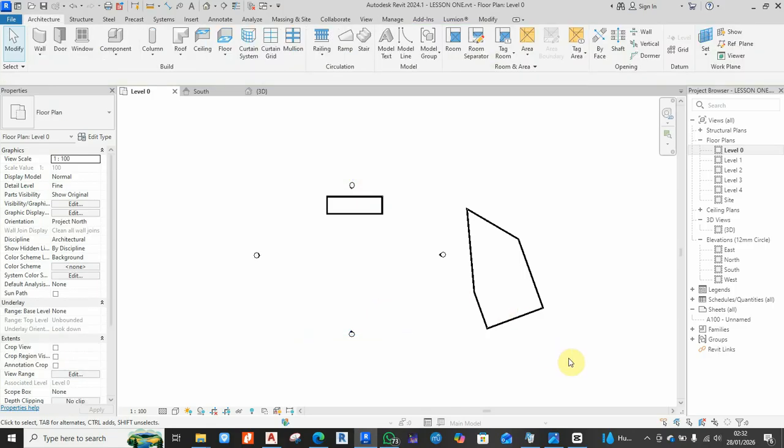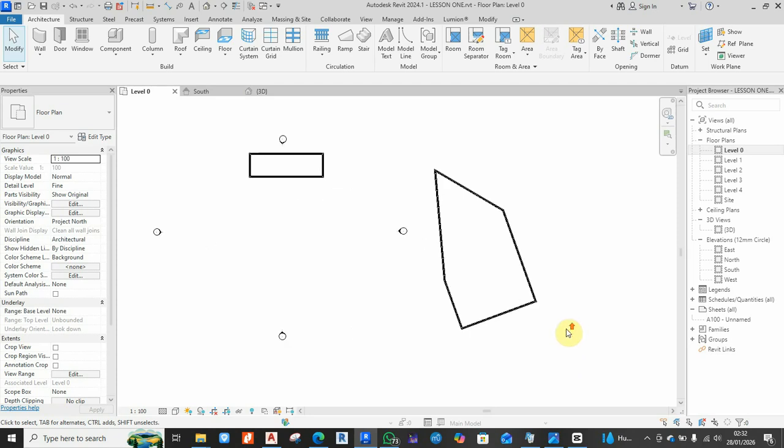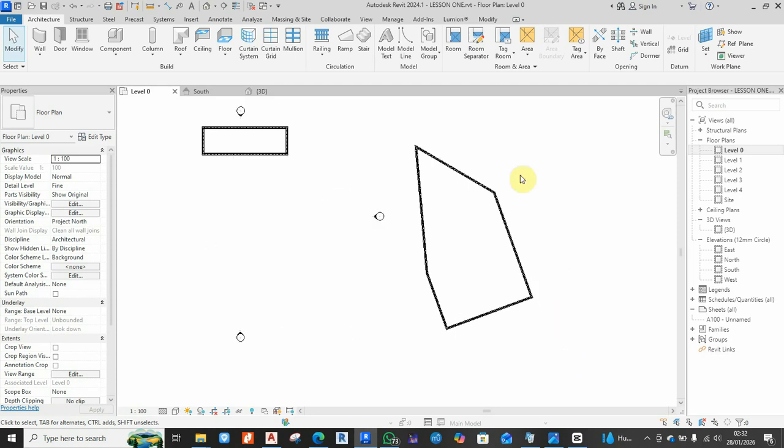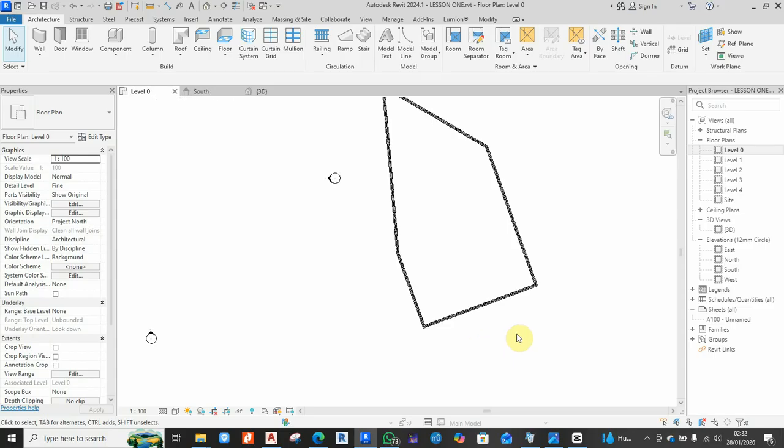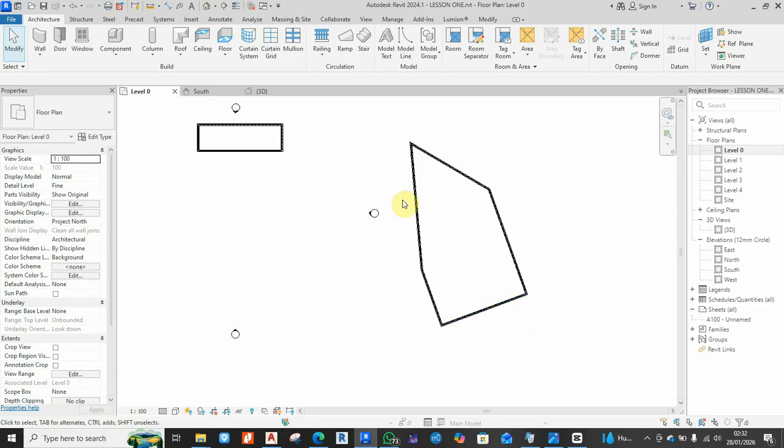Alright, I will select these objects and I will delete them. So there are a couple of ways of selecting. It's more like AutoCAD. If I click and hold my left mouse button, and I begin to drag, you see a selection box is coming. As I'm going from left to right, an element is only selected when that element is entirely within that selection box.